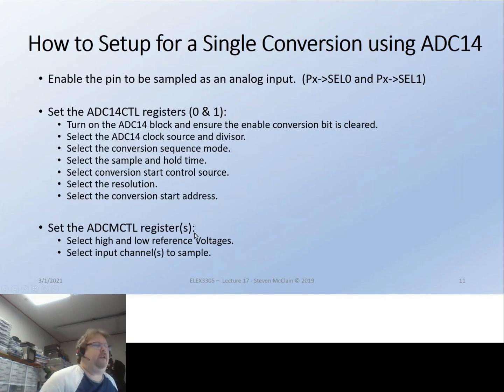Now you're going to use single channel sampling mostly, but if you want to do fancy, like for the joystick, you've got 2 voltages, right? So why not get 2 voltages in one conversion? It'll automatically do the 2, and then say, okay, I've got 2 new numbers for you, you ready? Otherwise, all that happens automatically.